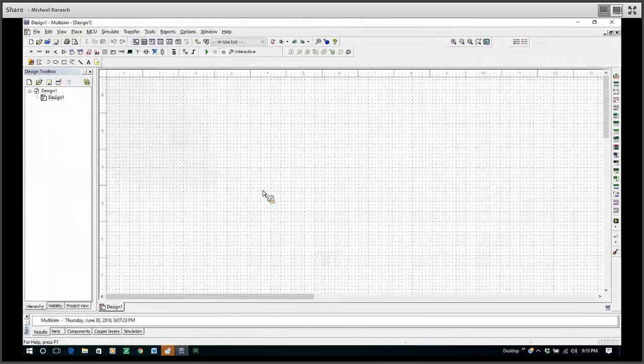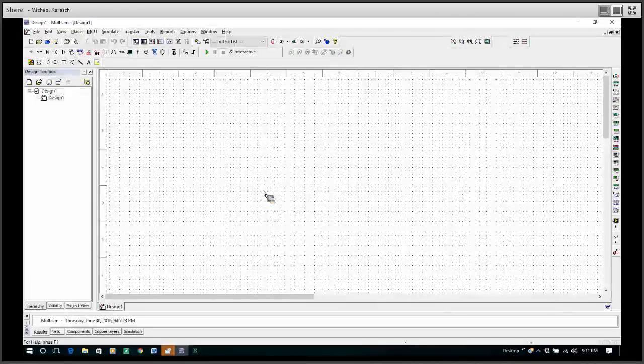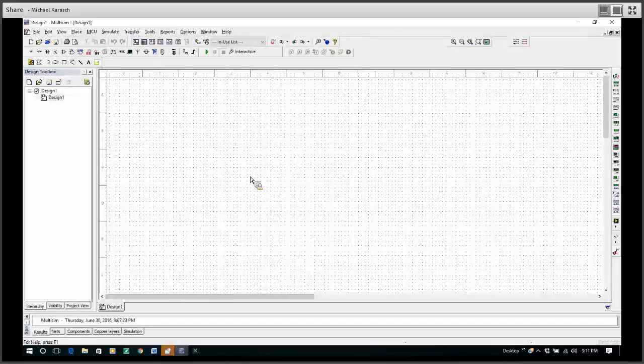Now, as we do this demo, we're going to actually build a circuit that is in activity 1.15b circuit theory, and I'm going to do problem number 2. In that one, we're going to use our meters and set up our meters and show you how to bring out components and everything. The method I like to use: they have a bunch of little icons up here. You can pull your parts and everything from these icons.